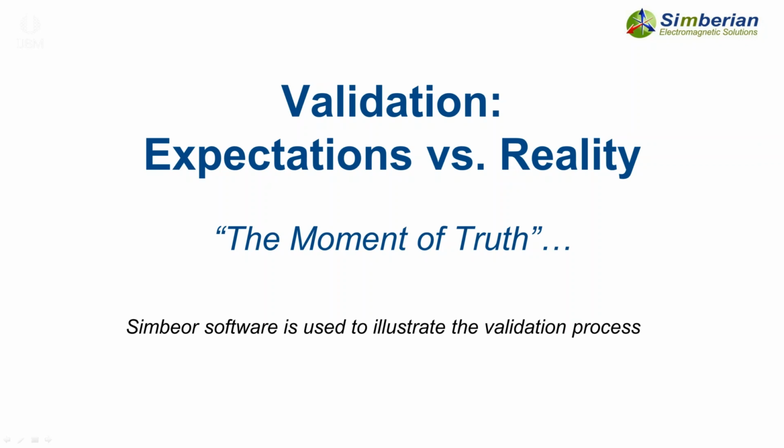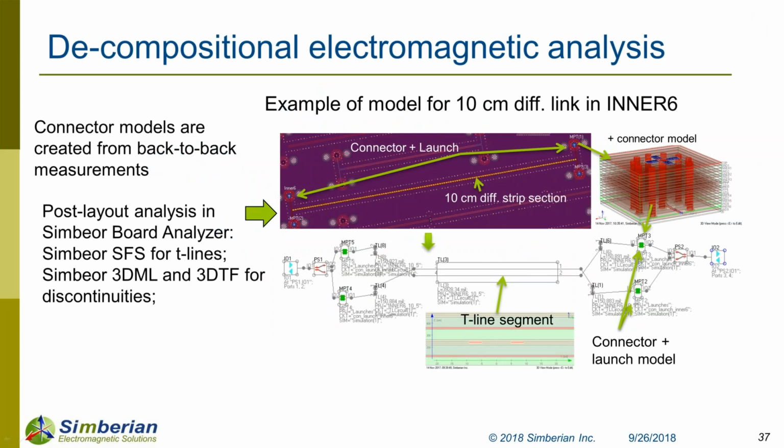Those are not statistical, but rather some observations on trace width, shape, and back drilling also. The cross sections reveal some problems in back drilling. At this point, we have material models, and we stop adjusting anything. So basically, we take this data and try to simulate the rest of the board without further adjustments.